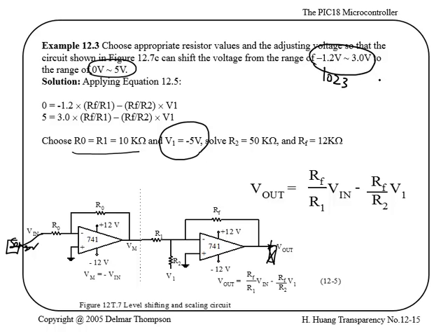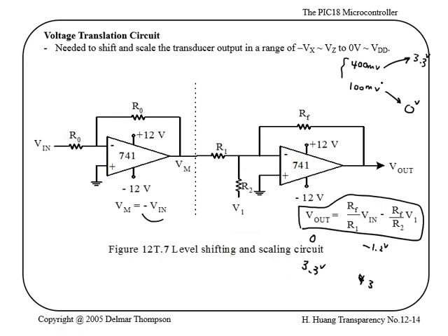So your resolution is indeed going to be 10-bit resolution. Here, if you map them, then you're going to map 1023 points between 100 millivolts and 400 millivolts, which gives you a lot of resolution, and that's going to be very useful.